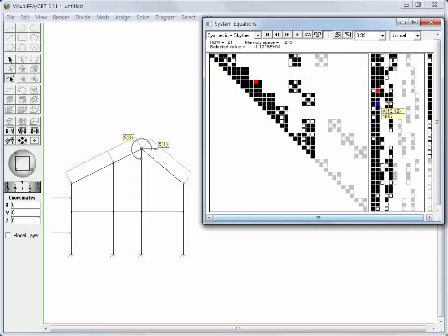You can easily identify the diagonal entries in the skyline assembly. Such examination helps understanding the rule of positioning the entries in skyline assembly. As an example, entries in skyline assembly can be traced by clicking the entries upward along a column in symmetric square assembly.